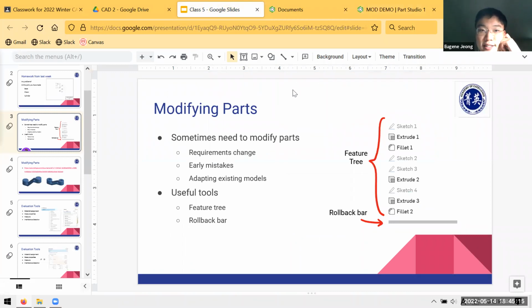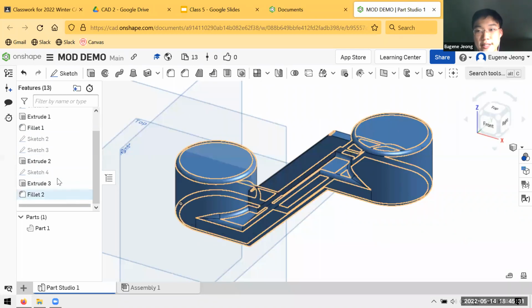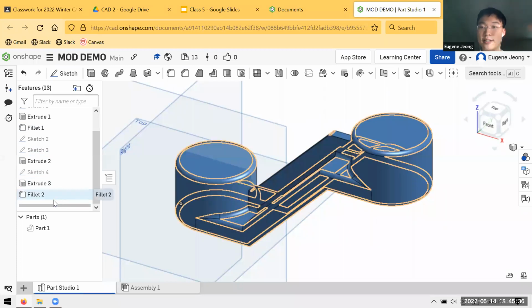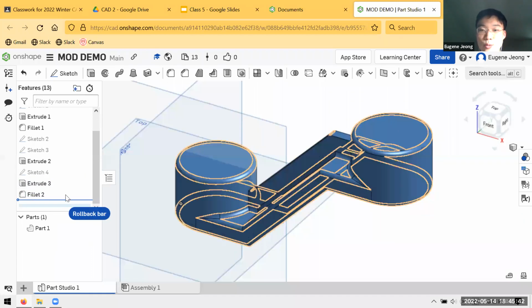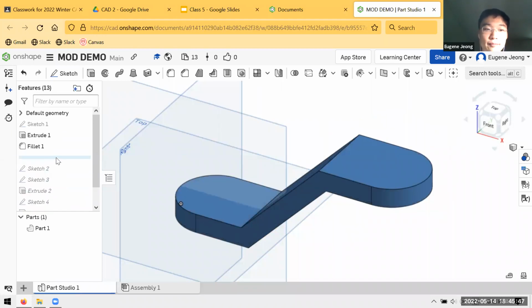These things will start to make more sense as you work with more complicated models, but for right now, if you haven't run into it before, you can take my word that it often makes sense to put your features in a certain order. When you create a model, you're often going to have a reason to go back and add more features, and a lot of the time it's easier to work with them when you've just created other adjacent features that are related to it.